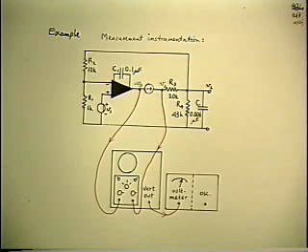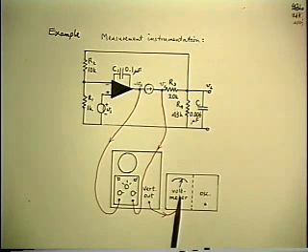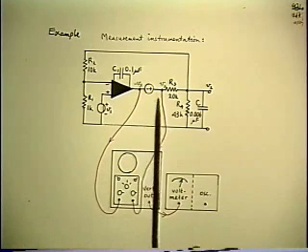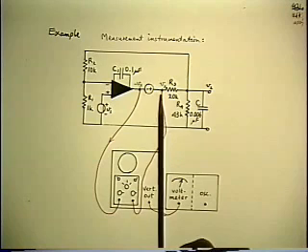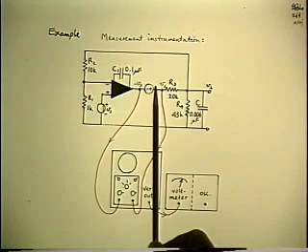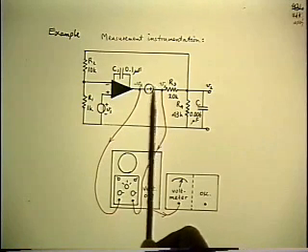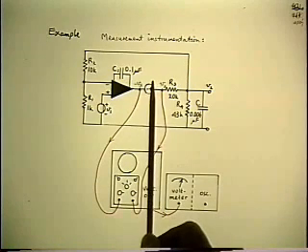The interesting thing is that you can measure the phase angle as well, even though the voltmeter measures only magnitude. And the key to that is, remember, these two voltages that we're measuring are 2 out of the 3 that form a phasor triangle, because we could define the sum of the two as Vz. We've already done that.